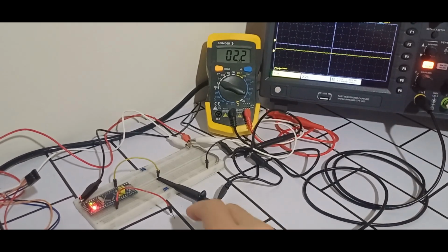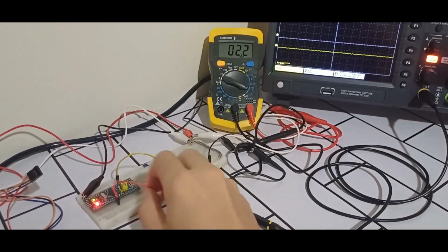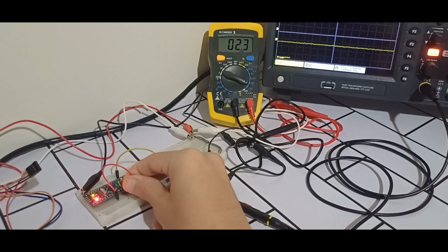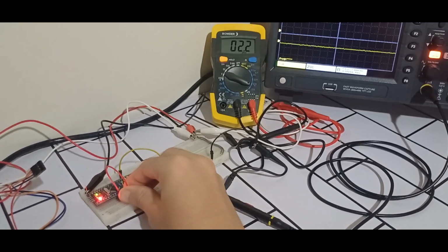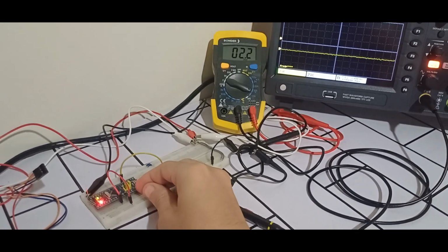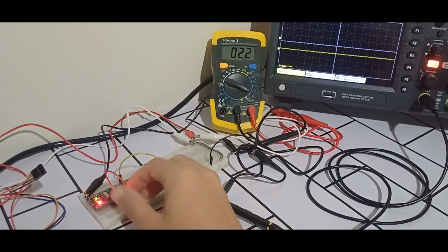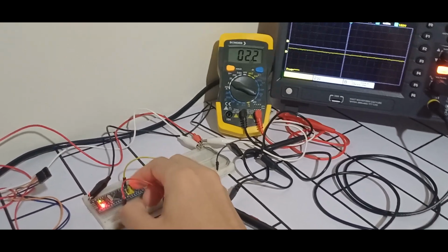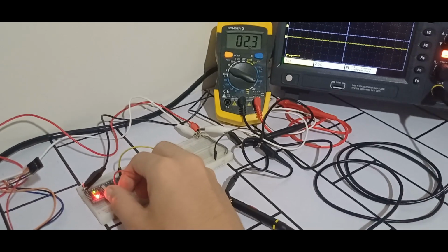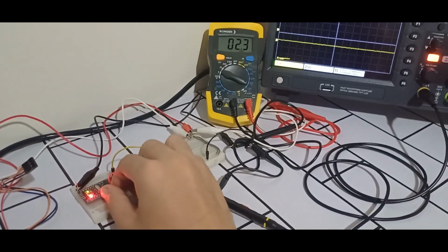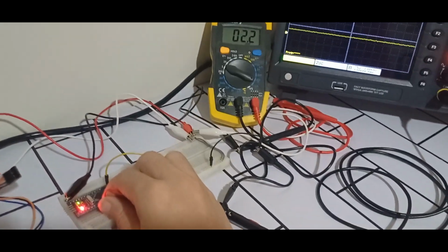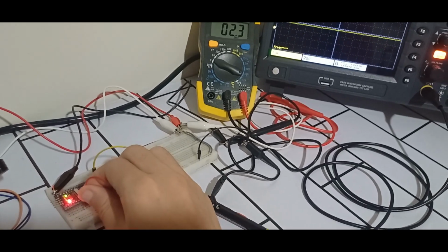If we try to exit the standby mode using the event detection, it does not work. We need to exit the standby mode by using the wake up pin, and when there is a rising edge detection, it will exit the standby mode.